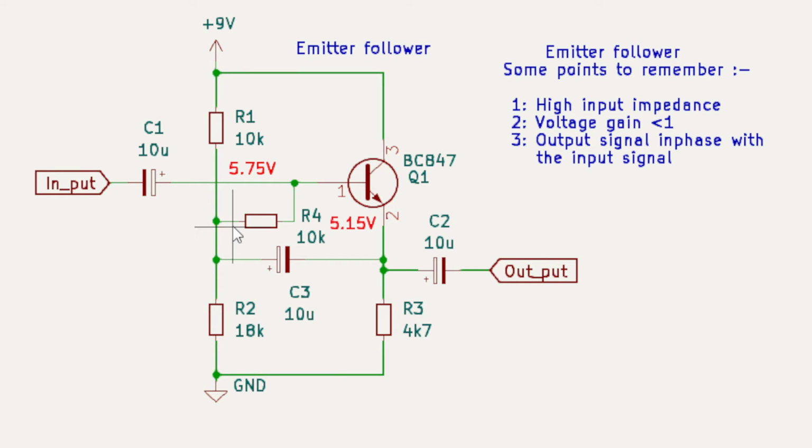And so again, we have the same voltage either side of a resistor, and if we have the same voltage either side of a resistor, then no current can be flowing, and if no current can be flowing, then that resistor is said to be of high impedance. We say impedance because for DC it's still there, it's still a 10k ohm resistor for DC, but for our AC it has a very high impedance, and that's what we're looking for.